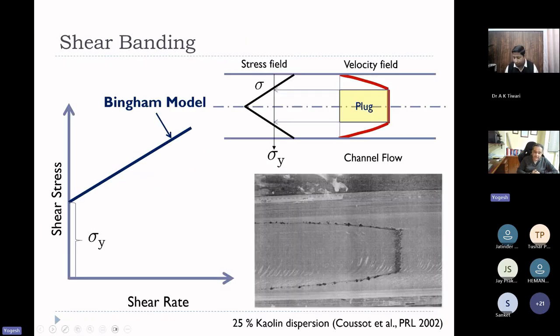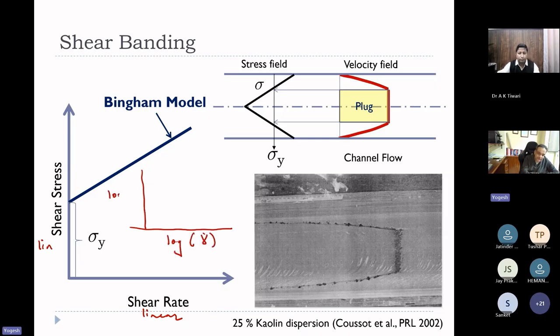All right. Then this is the Bingham model. And now keep in mind that I'm showing Bingham model by two ways. Okay. So this is one way of representation. This is linear shear rate, this is linear stress. All right. But if I plot log of shear rate and log of stress, whether on vertical axis you plot log or not, it doesn't really matter, but on the horizontal axis, if it's log, this phenomenon will look like this. All right. Okay. So you should keep that in mind.